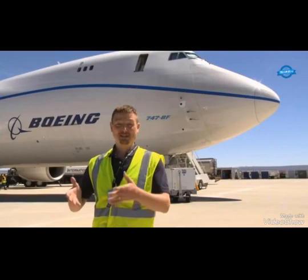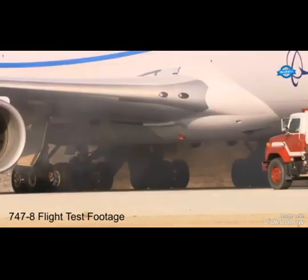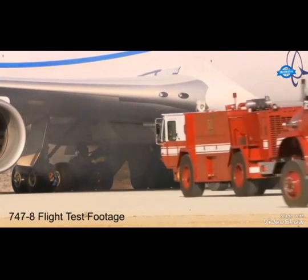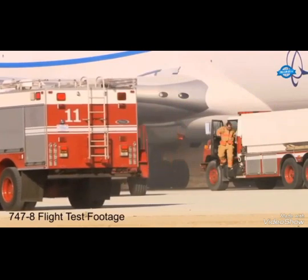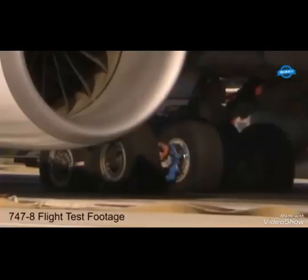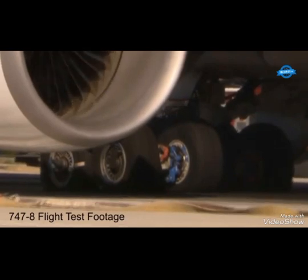To further simulate a real-world scenario, the airplane had to wait 5 minutes before firefighters intervened. This delay ensured that the aircraft could withstand the heat without immediate assistance. Special fuse plugs in the tires were activated to deflate them before any potential explosions. Once the 5 minutes elapsed, firefighters moved in with water to cool the brakes and tires. Although the tires and brakes would need replacement, the rest of the airplane remained unscathed.